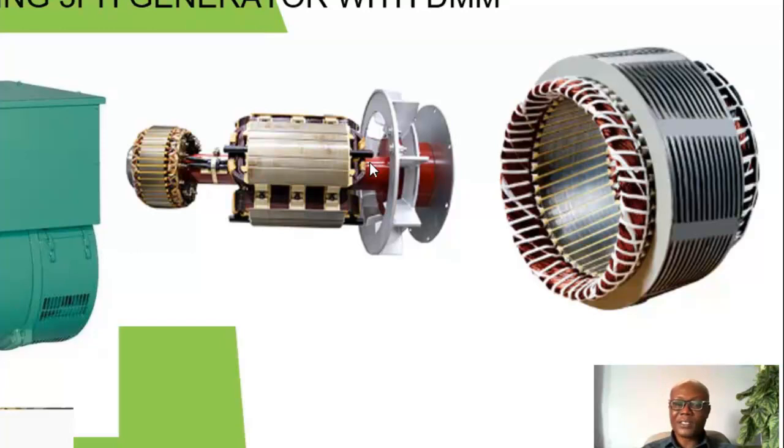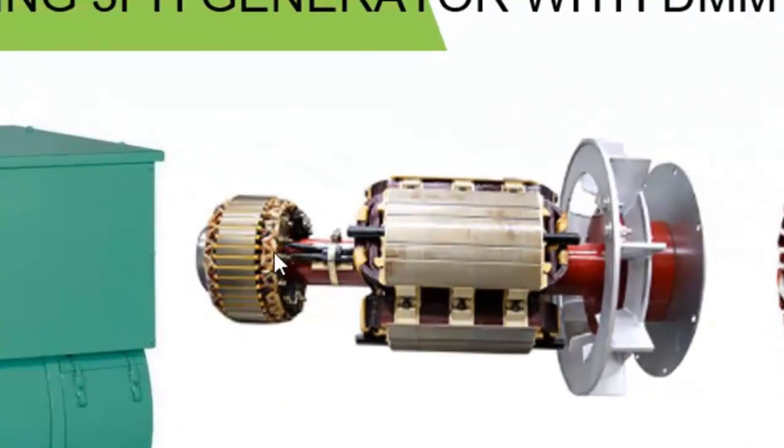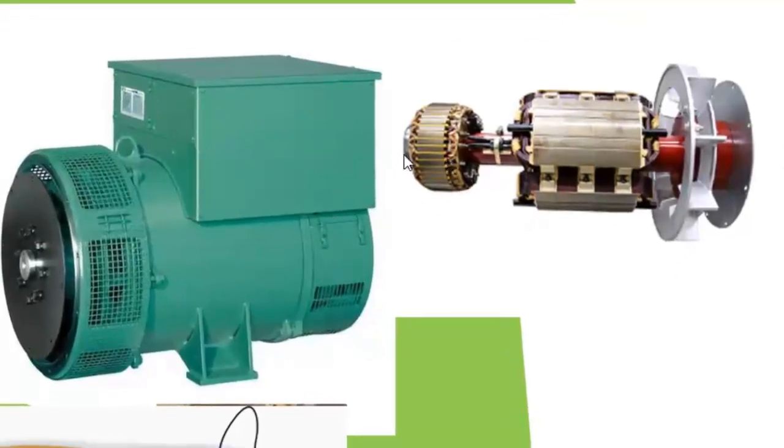Now, if you look at the rotor, you will see that there is another unit at the edge of that rotor. That is called the exciter armature. This is the exciter armature. It's like another small generator within the generator. It's always at the front end of the generator around this area. This exciter armature's work is to produce the voltage that will be responsible for magnetizing the field winding.